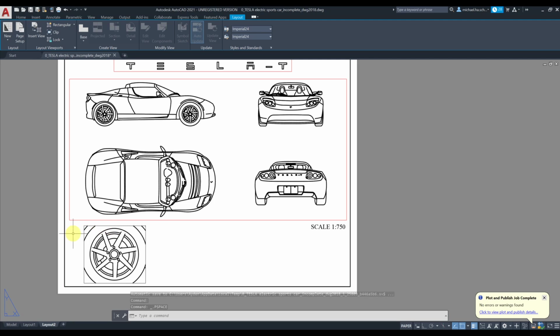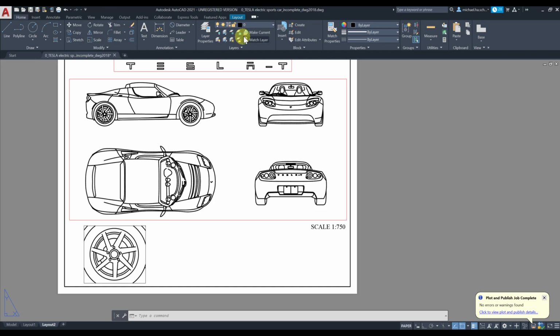Right now you're in the paper mode. On the paper mode, we're gonna go ahead in the viewport layer that we created. We're gonna draw a circle. Click on circle. You need a center and you need a radius. You can click anywhere.